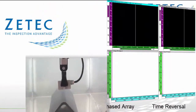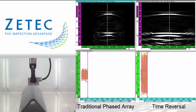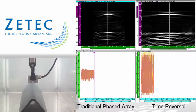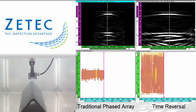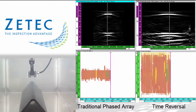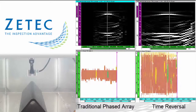For the curved section of the specimen, the same 1D linear array probe is used to demonstrate the better coverage when using time reversal. The traditional phased array channel covers approximately 10 millimeters of the specimen. At the same position, the time reversal channel has a coverage of around 30 millimeters. This extended coverage facilitates the detection of additional flaws.